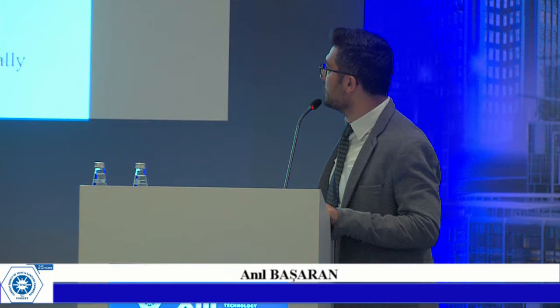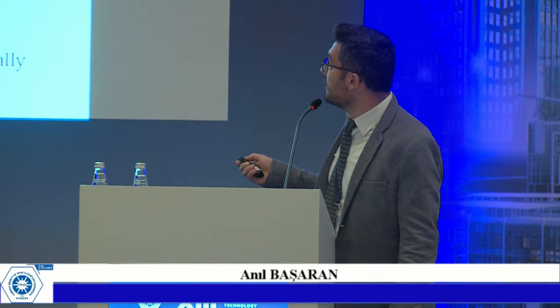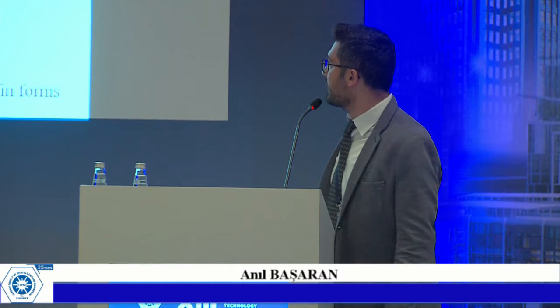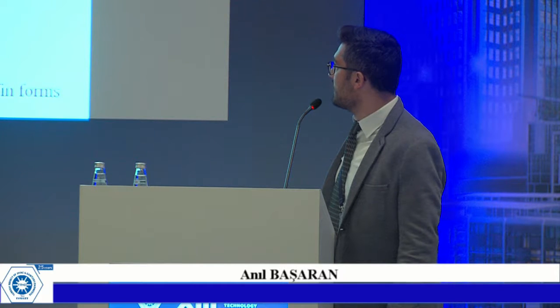Here, the triangular fin form shows the highest heat transfer rate due to its high heat flux and moderate heat transfer area. And figure 6 shows the temperature contour at 2 meters per second air inlet velocity. Here, in the triangular fin form, there is an increment of the temperature gradient. You can see it in red color. This means that there is an enhancement of heat transfer rate in the triangular fin geometry.